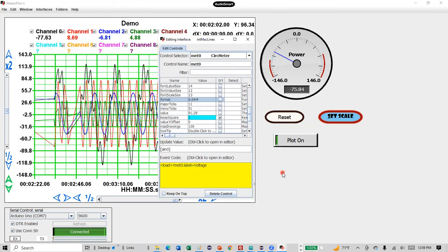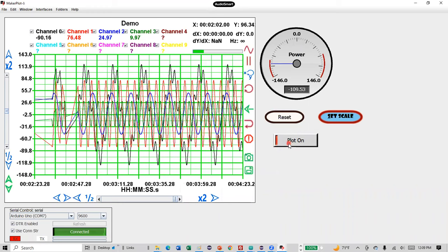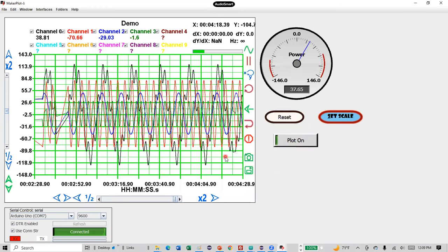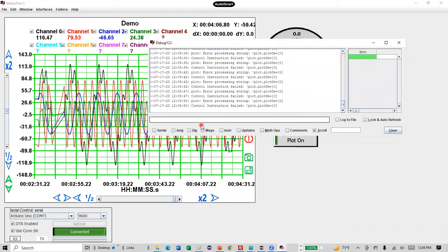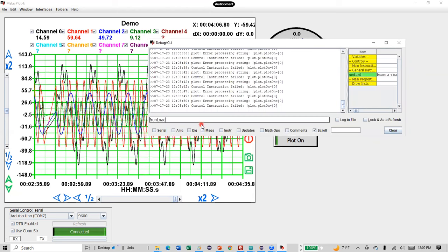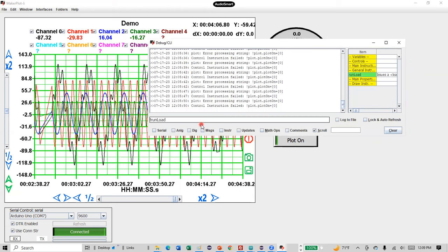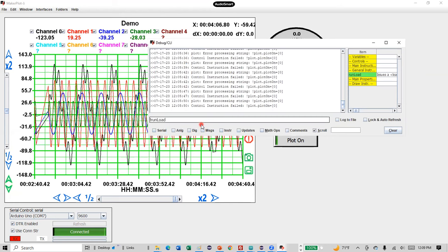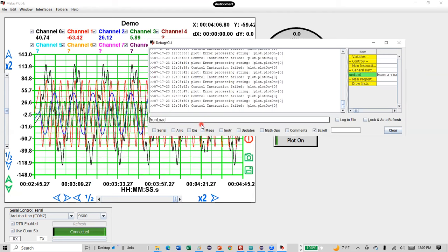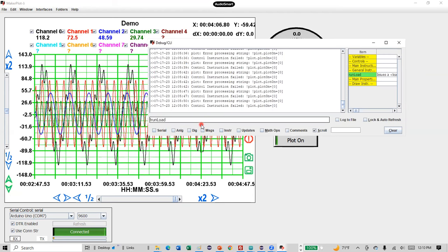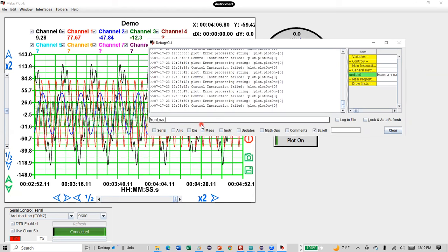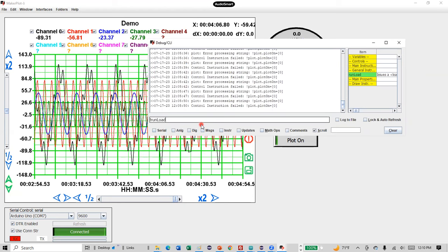Update code. Okay, so it doesn't change it when we click it because that's not the right event for it. I can test it by going into debug and doing run load. Run load will activate all the load events for all the different controls. That's built directly into an interface file when it's saved. One of the very last instructions is to run load, so it loads up all the controls and runs their load events.